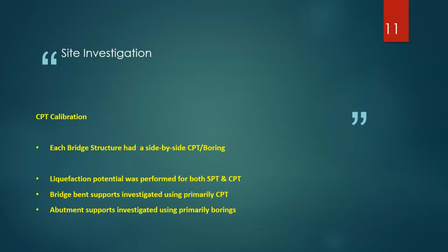Of course, there's a lot of data for CPT and boring comparison, but there's none for this local geology here in Orange County, and this goes a long way in your LRFD design of foundations later on and in building the database to give you even more confidence on how the CPT and borings correlate at the specific location, rather than just using generic data that is available in the literature.